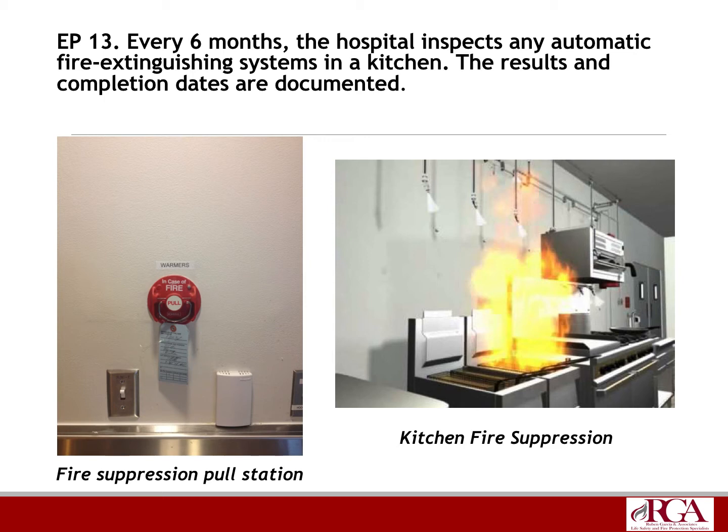Now, these fusible links are changed out every 6 months when they come out and do this test. So this is a semi-annual test. Make sure they're testing these every 6 months. It's very important that these are tested because, as you know, in a hospital, we have a lot of fire safety features. We really don't have a lot of fires, but when we do have fires, there are 3 areas that you're going to probably have a fire in.